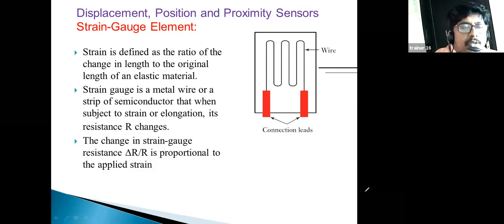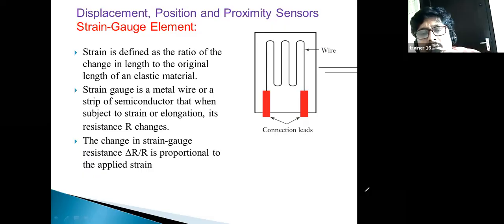All right. So here, about the strain gauge and the force, when the college is open, just go and check that load measurement device. At the end of the cantilever, we are adding weights on that board. On top of the board, the circuit diagram is mentioned, and the Wheatstone bridge is also there. So when we add the weight, the beam automatically undergoes a strain.